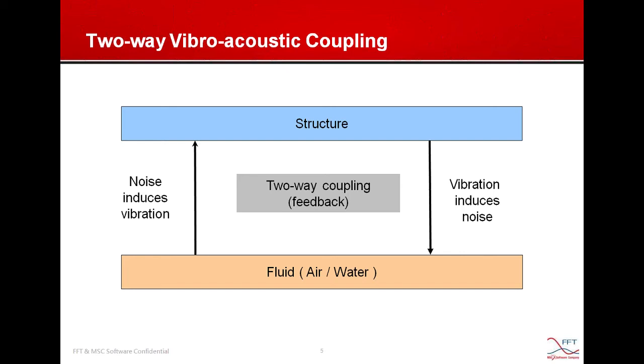Now, sometimes it is sufficient to consider only one-way coupling by making some decoupled assumptions, as we did in the last webinar for the gearbox radiation problem. But as a general purpose vibro-acoustic tool, a strong two-way coupling is many times necessary in order to handle the different types of vibro-acoustic problems.